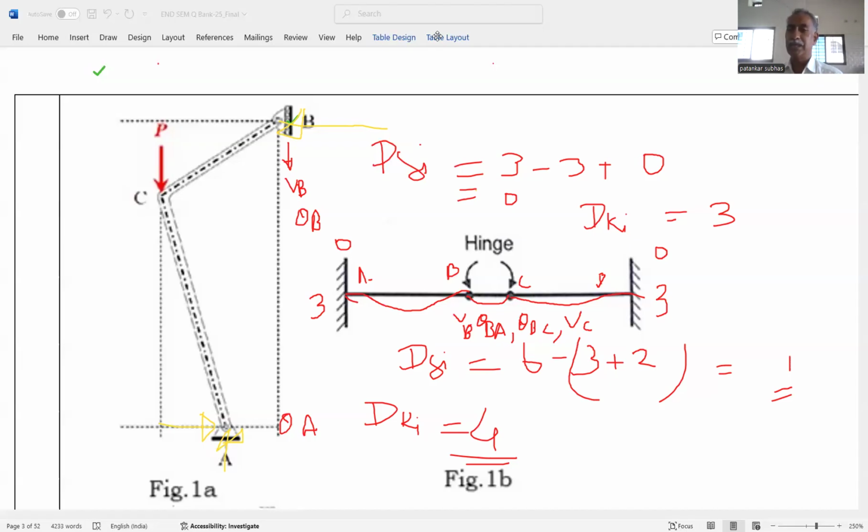And for the cantilever truss, generally we can analyze from the free end. And that's why even though both ends are hinge, external hinge, we can analyze, and that's why cantilever truss is always determinate externally and internally depending on the number of members. And that's why the equation, instead of M minus 2J minus 3, we have considered M minus 2J.